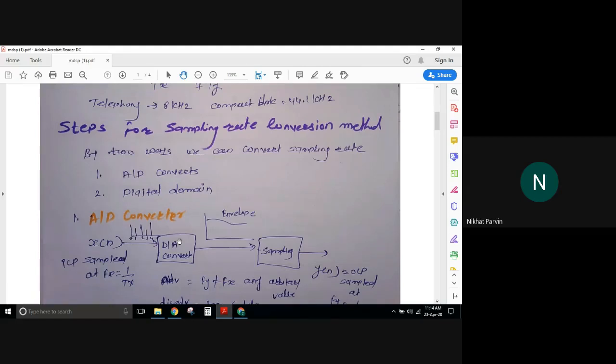So here you have a digital signal with you. Instead of doing something on the digital signal, first they are interested to convert that digital signal into an analog signal. In LICA you studied the different types of D by A converters, right? Using those D by A converters, you get some kind of envelope of this analog signal, because your input is discrete in time. Now you get a continuous time signal after conversion from digital to analog. Now this is the input of your sampler.